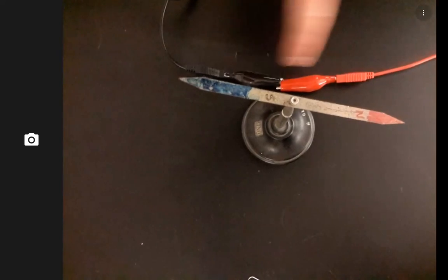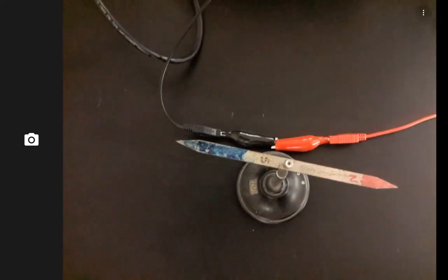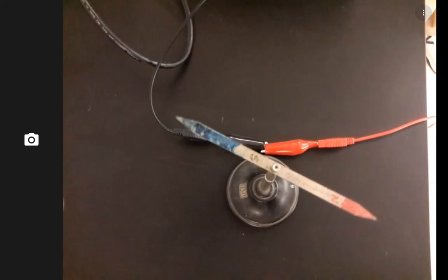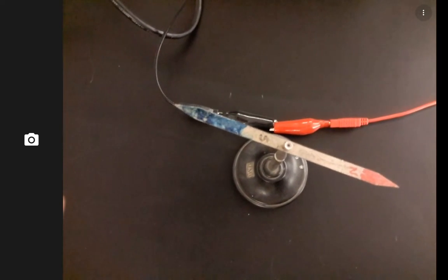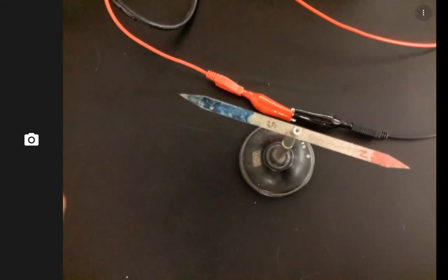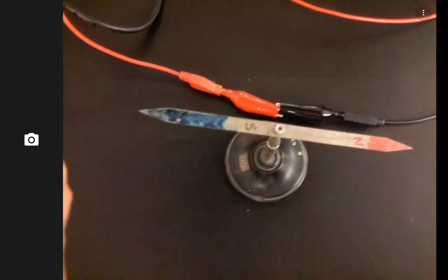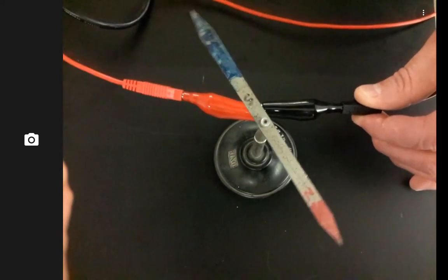Now, notice I had this running with the red on the same side as the red on my needle. And when I ran it, it rotated so red came toward me, which of course you can't tell which direction that is up there, but the red came toward the wires. So now I'm going to flip the wires so they're going the other direction. According to what we learned, what did that do to the magnetic field that's going to be created? It's going to change it, flip its direction. So now let's do it, and I'm going to actually lift it up so we have the bigger effect. And you see, indeed, the red now went away from the wire.